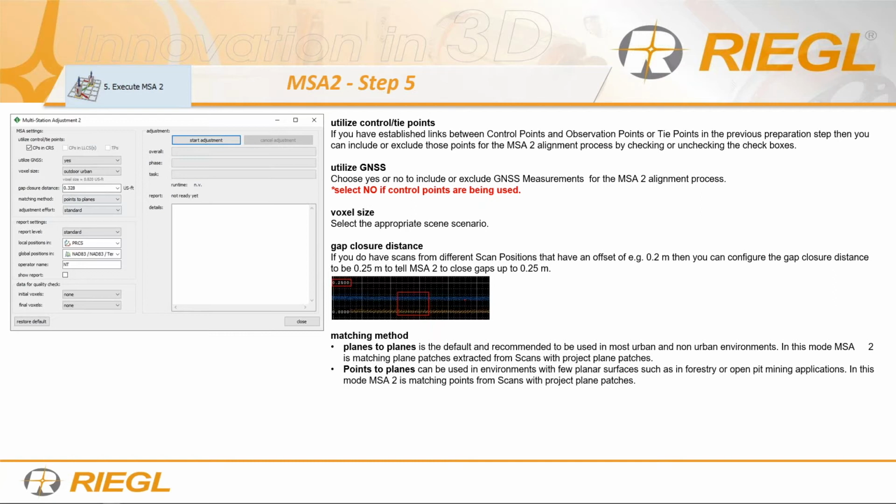If you are not using survey control, and if you're using RTK particularly, definitely hit yes. Okay, that's a very important message. So if you are using survey control, select no. If you are not using survey control and want to utilize the GNSS, especially with RTK, then hit yes. Or even with just the internal GPS, hit yes.